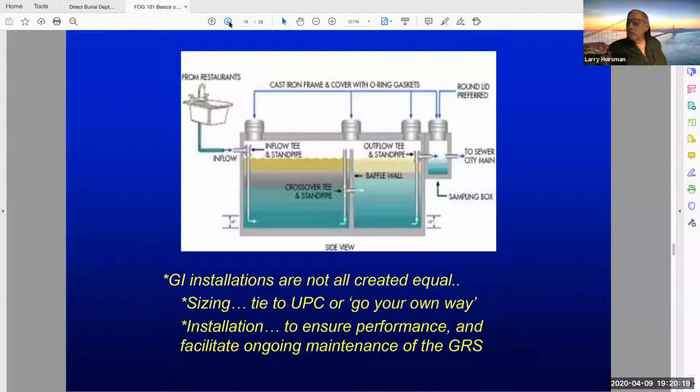So that would be a larger, normally in the ground, grease interceptor. Some of them actually sit on the floor just below the fixture. When I worked in the materials lab, we didn't have grease interceptors, but we had sand interceptors. We were washing dirt into the sinks all the time because it's part of the soil testing procedure. And you need to intercept that dirt before it gets into the sewage system.